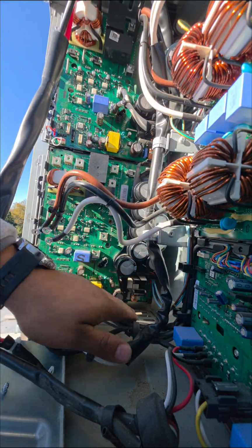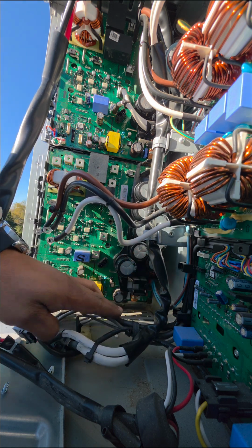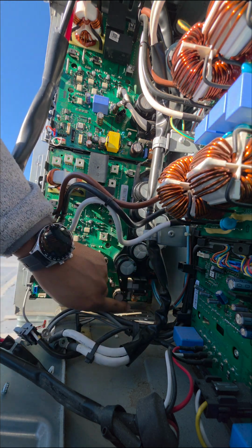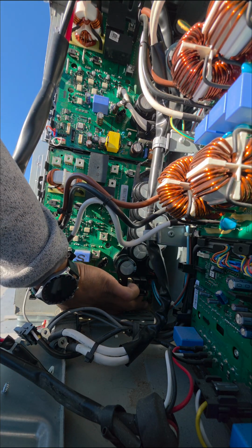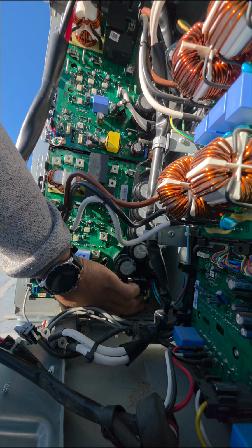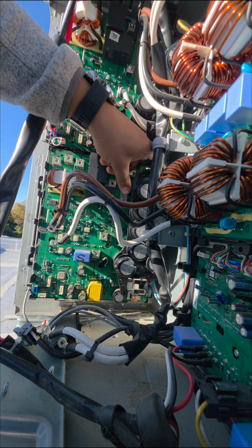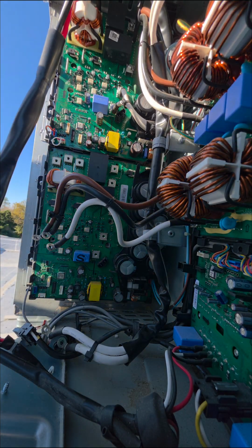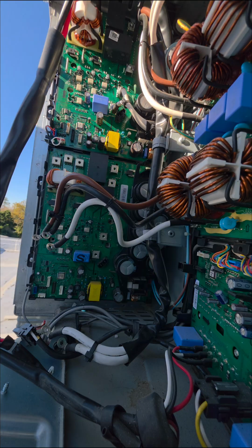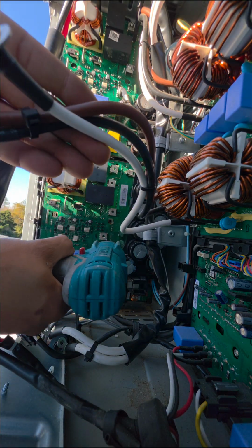Okay, so the board is in place. I've taken the liberty to get this connector in first because it's all the way back there, but the important thing is, if you have a look, I'm not sure if the camera will pick that up, but there's plastic retainers over here. Ensure that your PC board is in place over there, otherwise once you put these 4 screws in, the board's not going to make good contact or even contact with the heat sink.